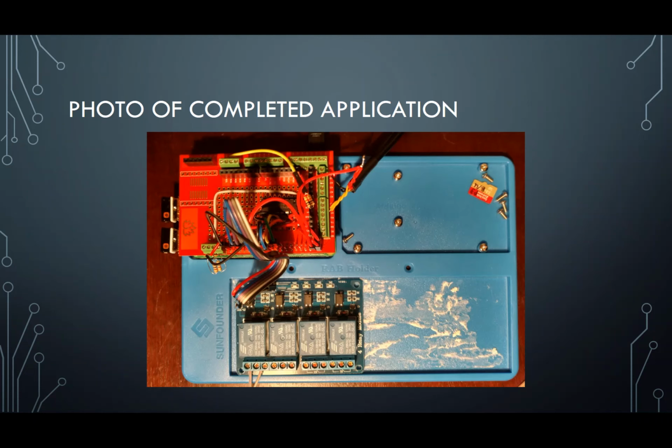I wanted to show you a picture of what it looked like on my desk when it was all finished and tested. The Raspberry Pi is on top and the 4 output relays are on the bottom. You will see the wiring here that connects the temperature sensors. That's actually done through better screw terminals in the field, but this was my testing scenario. Worked pretty well. And for the pressure transducer, it connects here, and I've got 2 resistors in there that split the voltage so that I can simulate the pressure transducer inside the house. So that's a picture of what it looks like, and it worked well inside, and I had absolutely no issues when I got it out to the pool housing to install it.